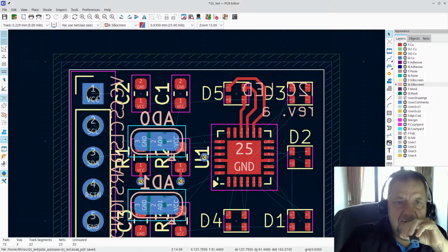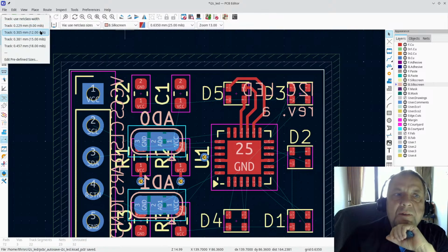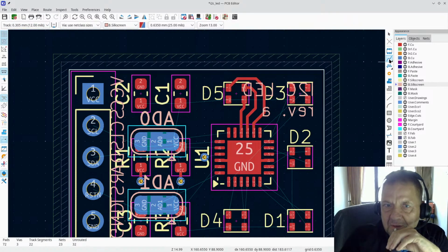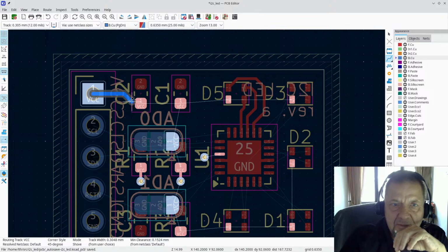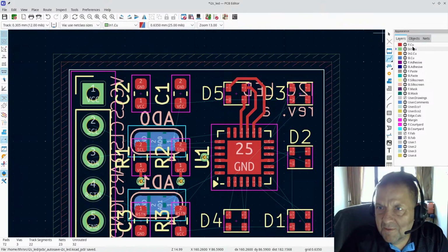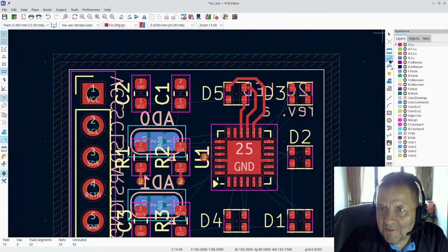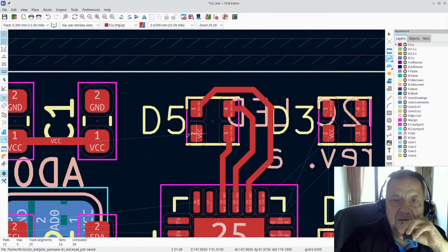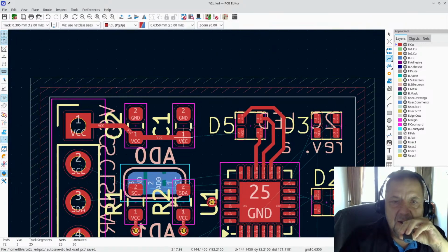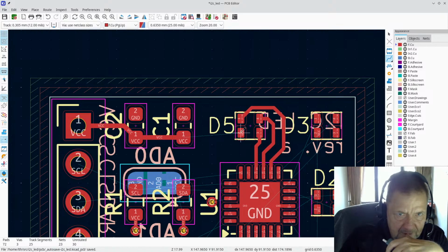In the case of power, however, it's probably a good idea to go up at least to the 12 mil. So let's start by doing a trace. You're on the wrong side. Front, and we can route that down, and then one straight over there. I'm not going to do that one. I'm going to do that, I think, later. But this one we can run here.